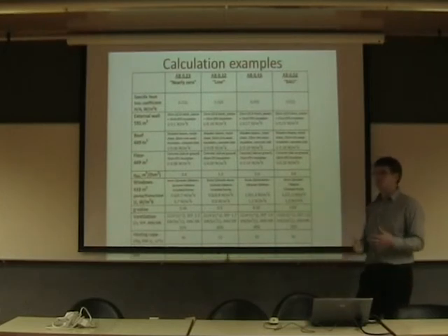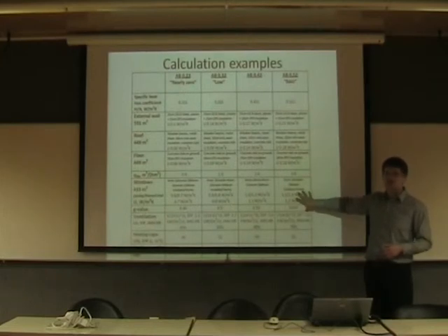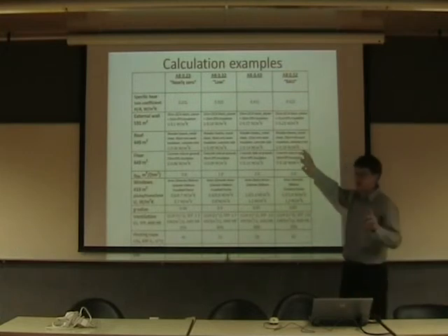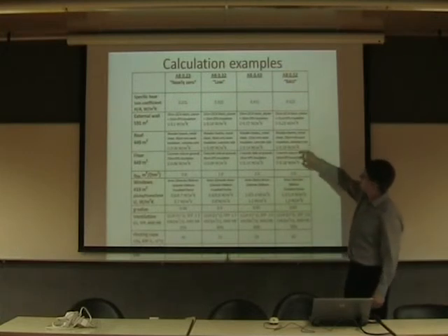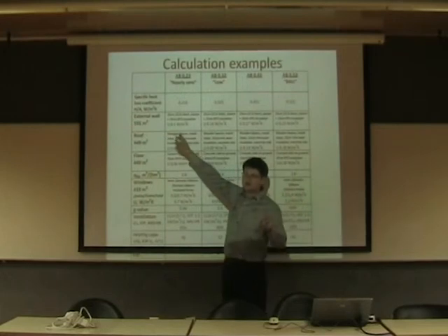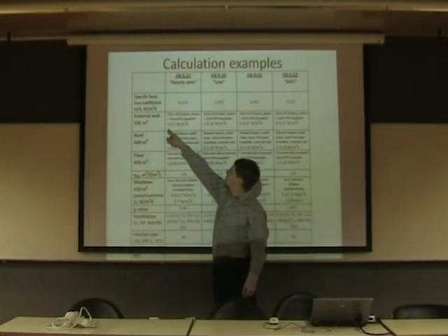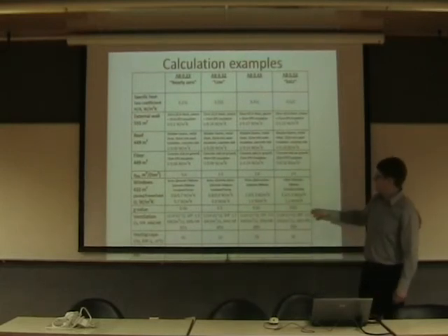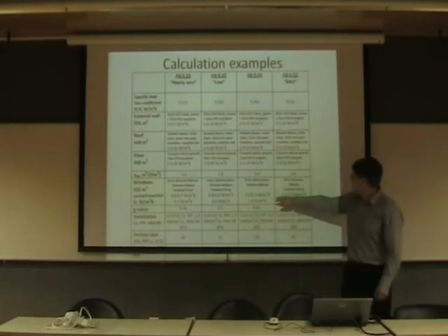When you are doing the group work, you can look at this sheet, which can also be included in your solutions. For the regular new building, the external wall U value is 0.23, but for the nearly zero energy building, the external wall U value is 0.1, and so on.